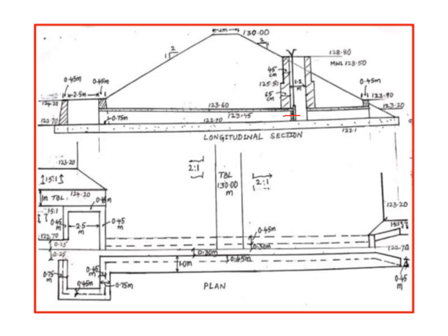I told you that the sill of the barrel is kept at 122.7, whereas the top of the RC slab is 123.6. We know the TBL is 130. We are given slope 2 is to 1. So we have fixed the top of the tower head at 128.8. Now you know that this is the top here after the water flows. So it has to go to the cistern.